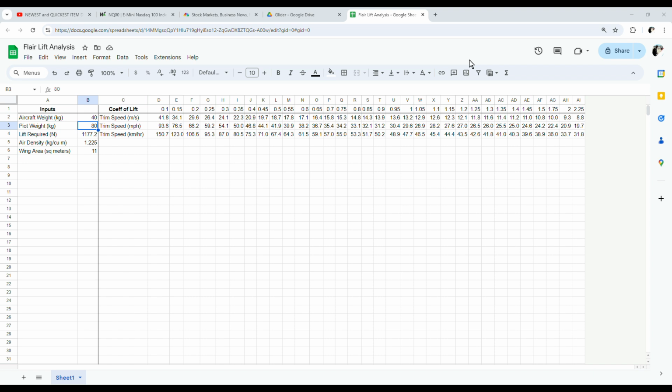So if he's trying to get it slowed down to 37, but he can't because he weighs so much more, that's a problem. And that could cause somebody to dump flap in a big hurry, or put even more flap in, more than 20, maybe put in 30 or 40. And no matter how you look at it, it's just worse and worse and worse. The only thing he could have done here is fly the aircraft faster and land faster. And maybe they didn't really just stop to think.